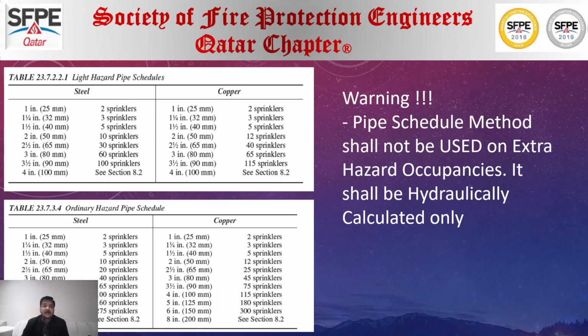And also they have given a pipe schedule chart. So rather than looking into the hydraulics chart from the Hazen-Williams formula or from the Hydraulic Institute to determine the flow rate, the friction, and the velocity, NFPA 13 gives us a simplified table, which is also derived from the Hydraulic Institute chart based on Hazen-Williams.